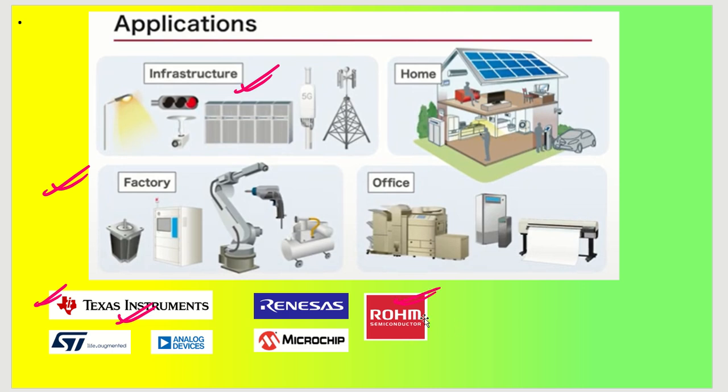We will be showing you several different manufacturers' current sense amplifiers that we have utilized in our applications, such as IPM modules, intelligent power modules for BLDC motor drives in water pumps, air conditioner designs, or robotic arm designs. Right now we will consider only one device, and we'll explain through its data sheet how it can be utilized in a particular circuit, okay?